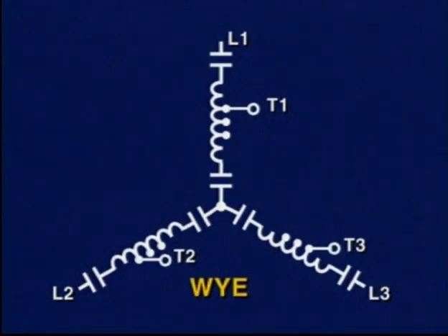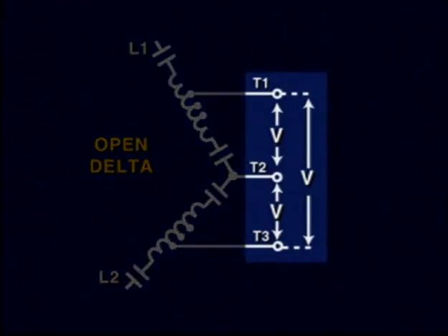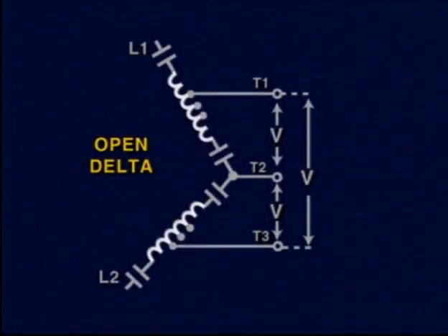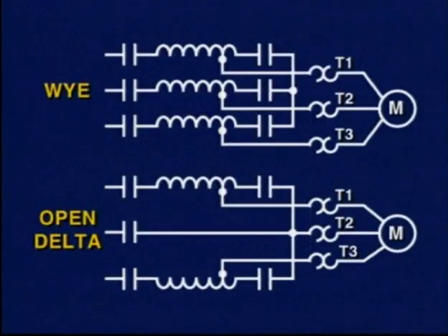The wiring diagram for the motor circuit may have 3 autotransformer legs connected in a Y configuration, or it may have an open delta type configuration. Note that the 3 voltages to the motor are virtually the same, and the 2-coil open delta configuration usually produces a negligible imbalance in starting voltages. The control circuit for the open delta configuration is the same as for the Y configuration.